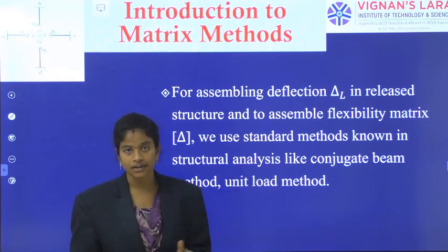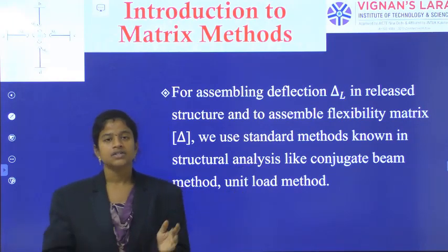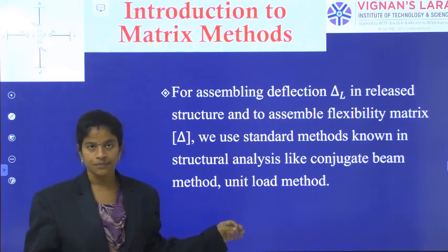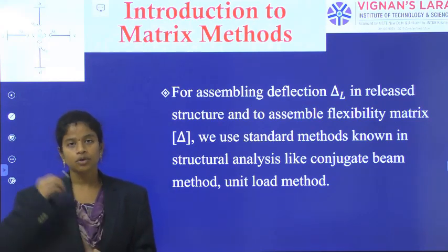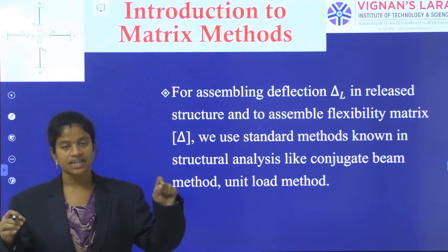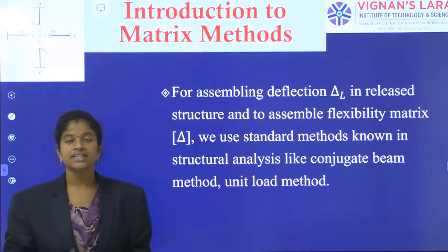The moment area method we write, right? So in the same way it will also come, so the area of the bending moment diagram will be involved. In the unit load method, removing the external load we apply a unit load. That's why it is the unit load method. In the strain energy concept also we have given the unit load method concept.